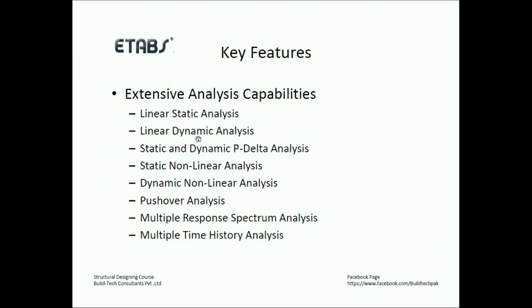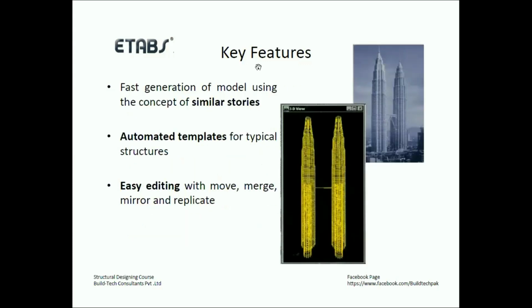These are different analyses that can be done in Etabs. I already told you about linear static analysis, which is the equivalent lateral force procedure. Then there is linear dynamic analysis, and static and dynamic P-delta analysis can be done on Etabs. There's a pushover analysis, which is done to check the performance of existing buildings. Then there are multiple response spectrum and time history analyses. All these can be done on this software.